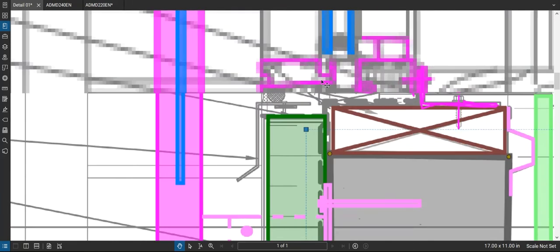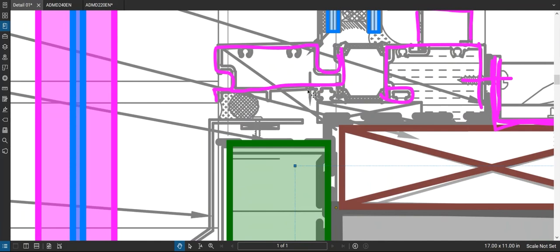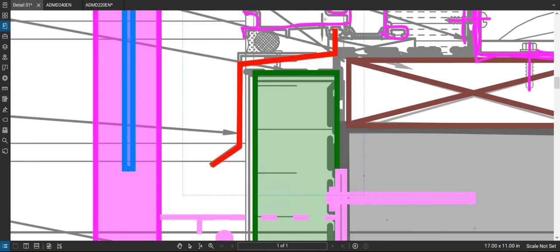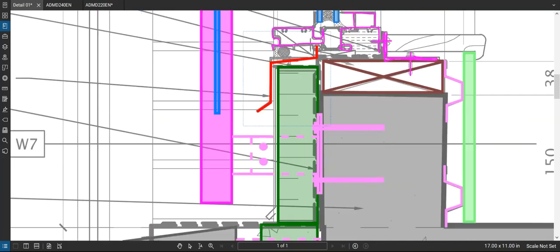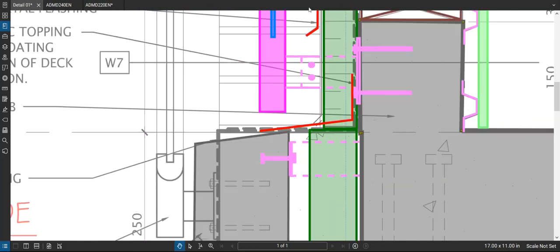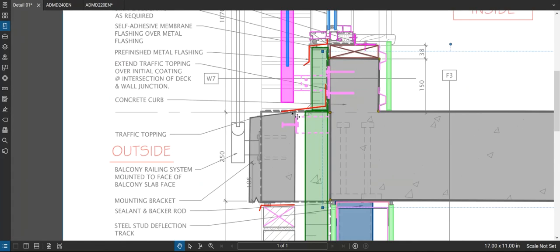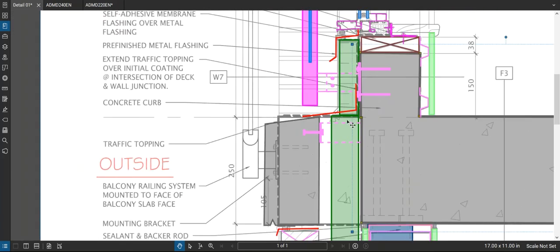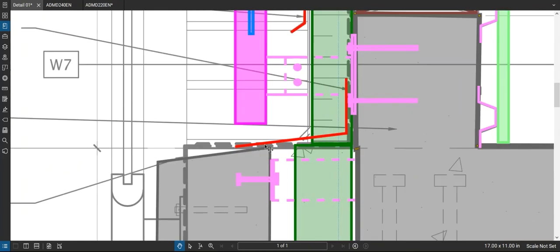And then here, I'm just looking at the frame, and I can see an arrow here, so it looks like there's a weep hole right here in this frame system. So what I'm thinking happens there is probably the flashing wants to be something like that. So when it weeps out, it comes down the flashing like so. I've added a flashing down here. I don't want any water from above, basically in the more exposed area, getting into the cavity space of here. Let's try and keep that out. So any moisture that's accumulating up here, let's get it out of the system right here. So I put some through wall flashing there.